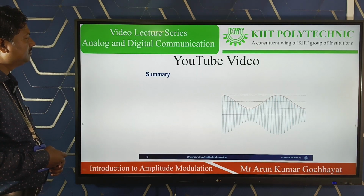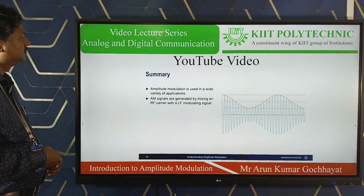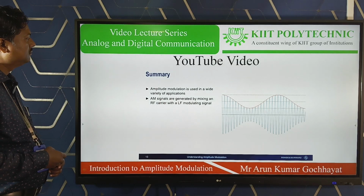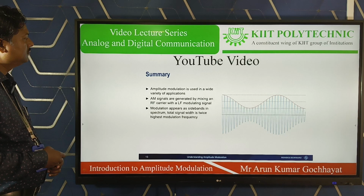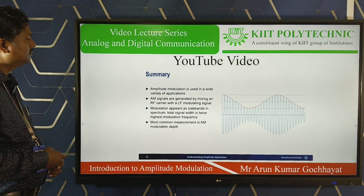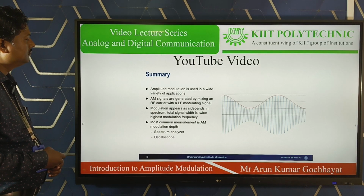So in summary, amplitude modulation is used in a wide variety of applications, such as broadcasting, avionics, and EMC. AM signals are generated by mixing an unmodulated RF carrier with a low-frequency modulating signal. If we look at an AM signal in the frequency domain, we see modulation appearing as spectral sidebands, with the total width of the modulating signal being equal to twice the highest modulating frequency. The most common measurement made on AM signals is AM modulation depth, or modulation index, and this can be done using either a spectrum analyzer or an oscilloscope.